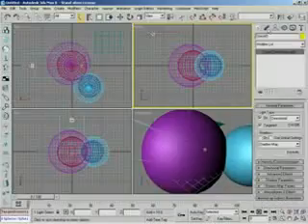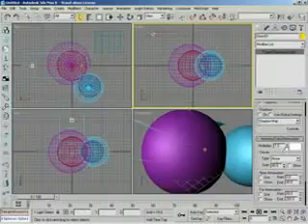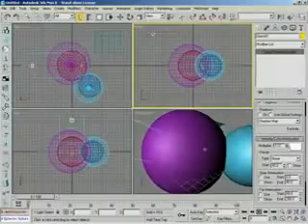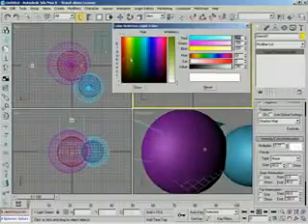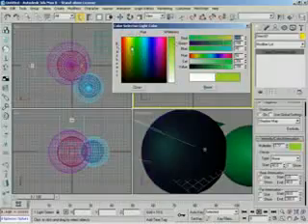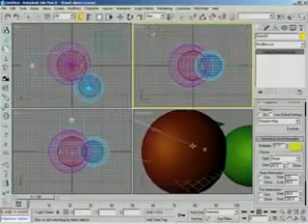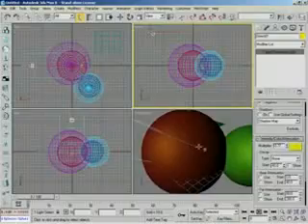And the next tab's pretty fun, too. It allows you to modify objects. Right now I have a light selected. You can see right here a target directional light, and underneath it we have a bunch of parameters all associated with that light. If I come down here to intensity and color and open that up and take my multiplier and start turning it down, it's getting awfully dark in here. Or if I start changing my color into some really scary, audience-nauseating color, there we go. I have really changed the colors of those guys. I am now modifying. That's the key thing.